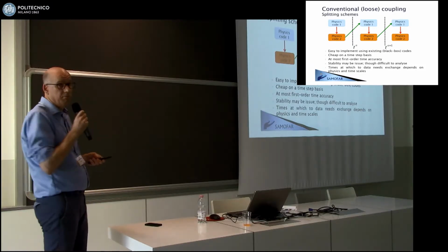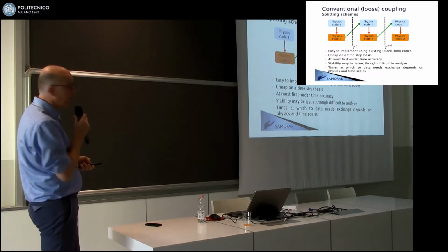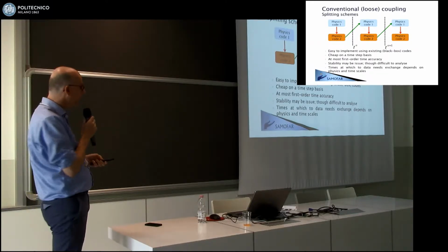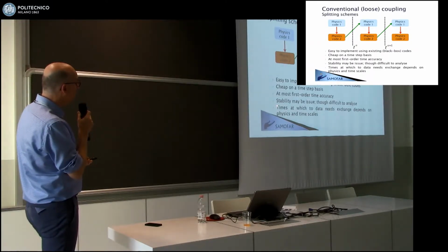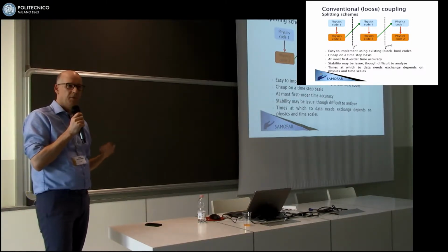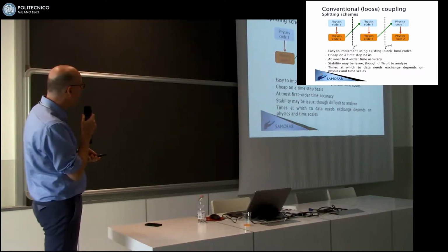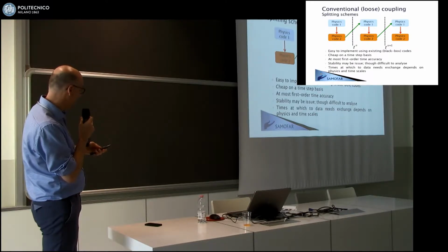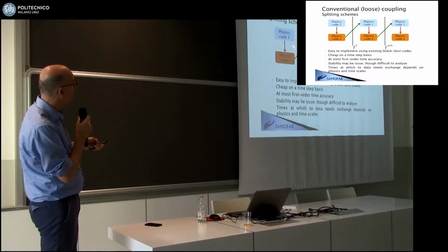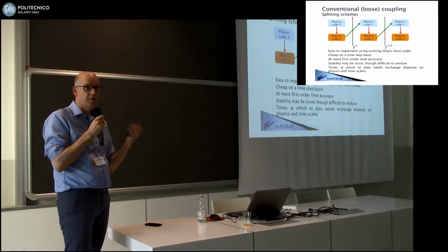So up to maybe 10 years ago, most of the work was done like this. And quite honestly, there's really not all that much wrong with it. Most of the time it does work. One of the problems, if you're really looking for very high order accuracy, you cannot do it like this, because at most this will be first order time accurate. Now, the other thing is stability. Even if both of these codes are implicit, you're still restricted in time step, just because you're not iterating.